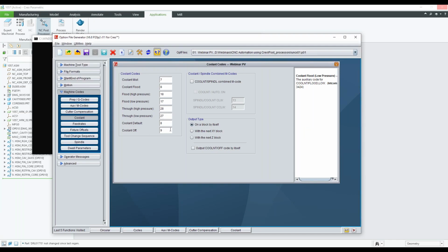These are all things that you have to know, and you have to activate these when you create your sequences. The default NC stuff in Creo is not going to have coolant on at any stage. So you need to do that for each sequence, or you have to set your site file so the coolant is always on.